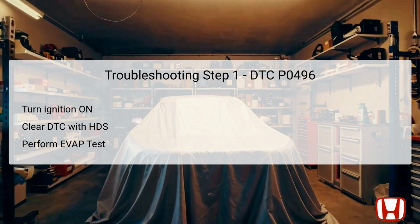Next, the technician should clear any existing DTCs using the Honda Diagnostic System, HDS, which will allow for accurate testing without previous error codes interfering with current diagnostics. Following this, the technician selects the EVAP test option in the inspection menu and then proceeds to the function test of the EVAP system using the HDS.